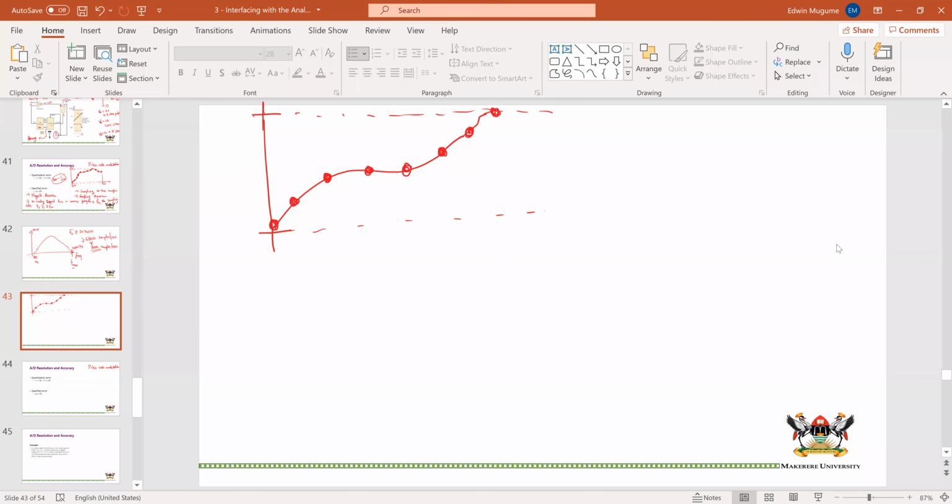Now, once we take the samples, how do we encode them? That is the process of encoding. When you're encoding something, you're getting a value and giving it a code. In this case, a binary code, if we are doing binary digital conversion, or some other binary code, but let's do binary. So usually you get this range and divide it into something we call quanta. Quanta is like, you quantify. So the quanta comes from the quantification of different levels.